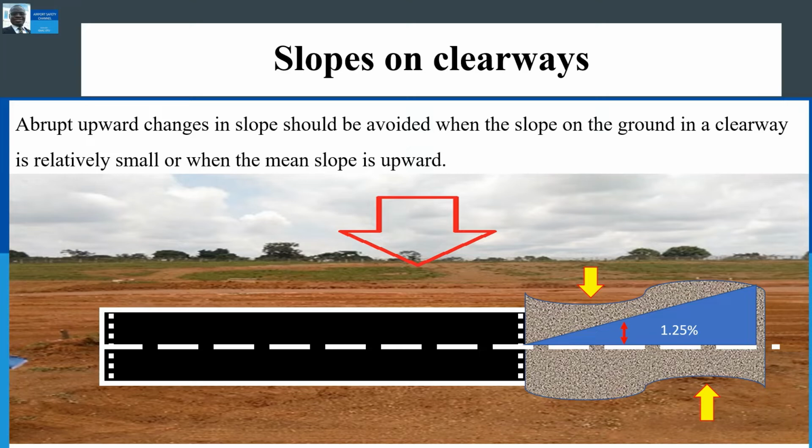An example: because of transverse or longitudinal slopes on the runway, on the shoulder or strip, in certain cases, the lower limit of the Clearway plane may be below the corresponding elevation of the runway, so that the runway or the strip is higher than the Clearway plane.